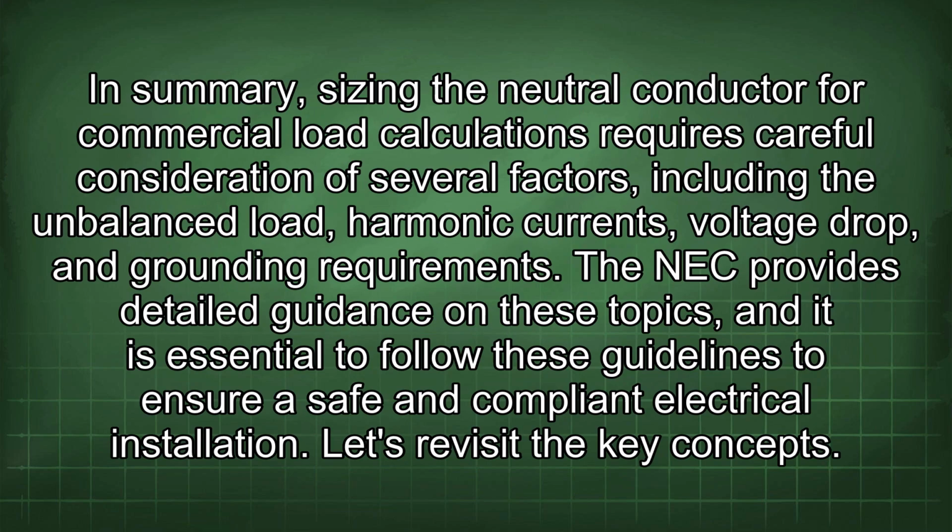In summary, sizing the neutral conductor for commercial load calculations requires careful consideration of several factors, including the unbalanced load, harmonic currents, voltage drop, and grounding requirements. The NEC provides detailed guidance on these topics, and it is essential to follow these guidelines to ensure a safe and compliant electrical installation.